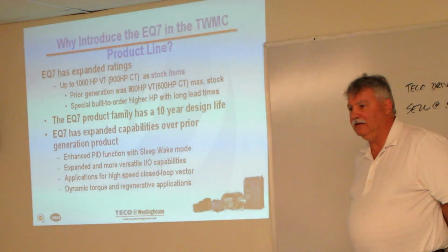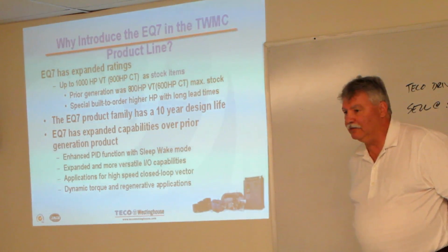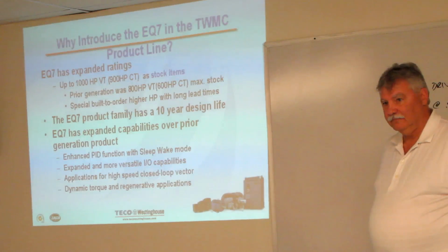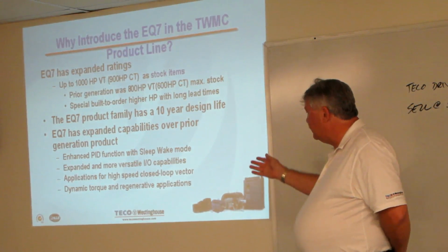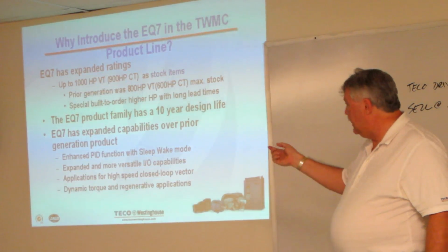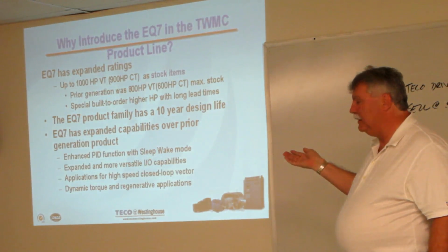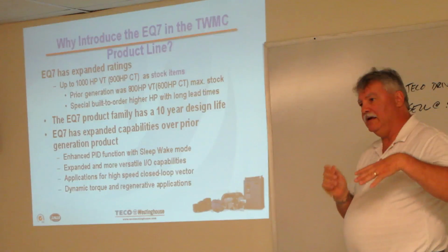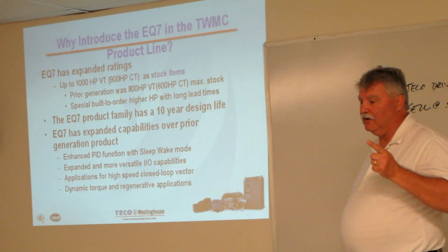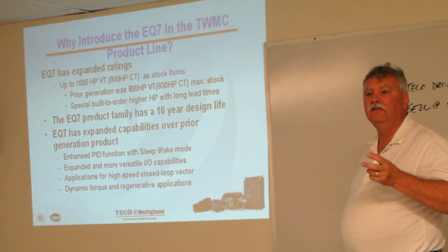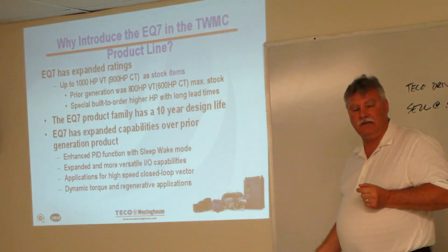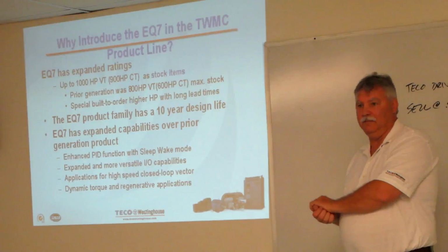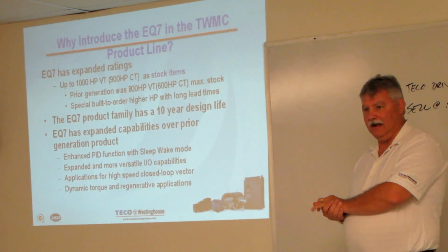can bring that directly into the drive as an analog input. It can respond that way. I said we put in the versatile I/O capabilities, and I mentioned before how we can bring something in either as a normally open or normally closed signal, and we can configure it and make it work out. So we don't ask the customer, say, well, you're going to have to get a relay and send me over the contact in the other state.